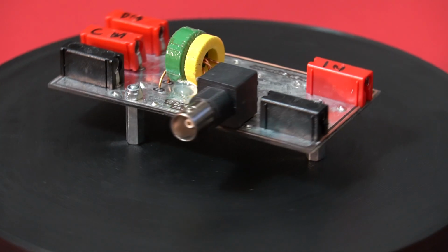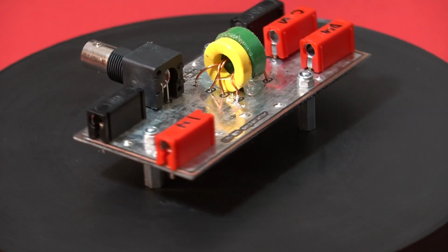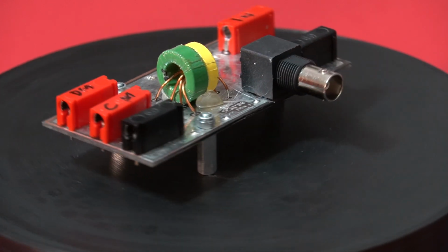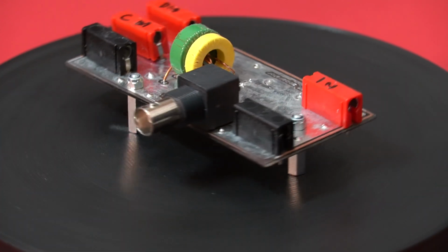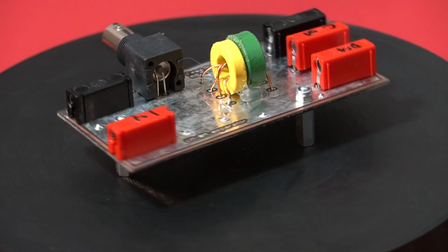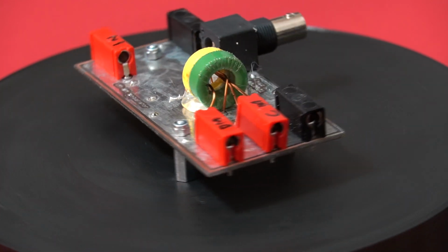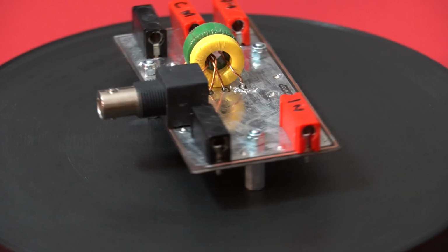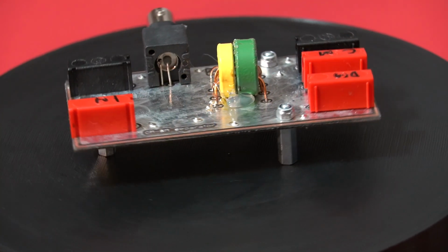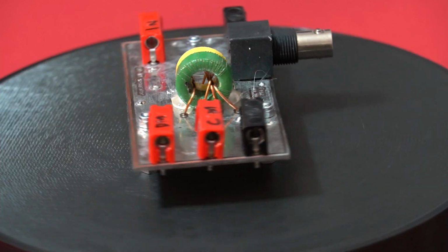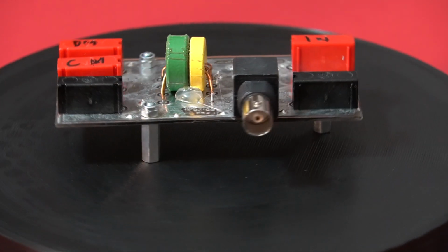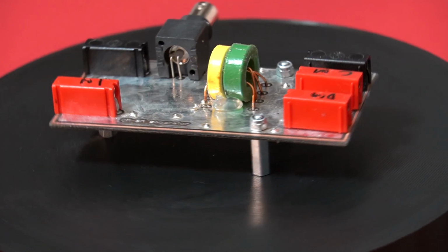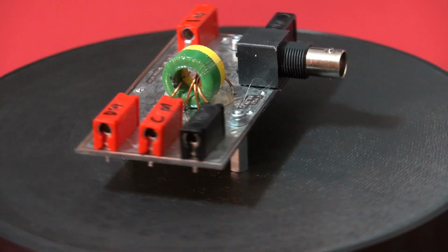Now, to build this thing, I used a ferrite ring core, and each of the windings is a single turn going through the core, and I saw this trick somewhere to create a wideband transformer by using different cores in parallel. And I tried to implement that. So the green core is from an old 10 millihenry common mode choke, so it has really high permeability, but because of that, this core won't really work well at high frequencies. So for that, I added the yellow core, which was from a 10 microhenry inductor, so it has much lower permeability, and this core should step in once the frequency increases.